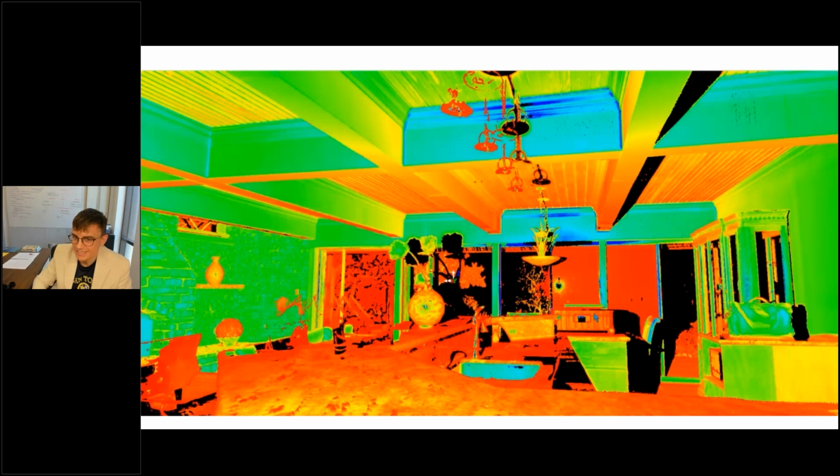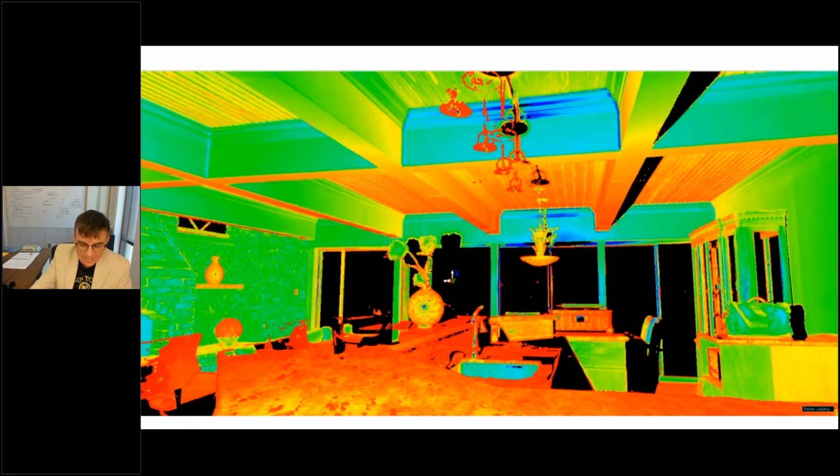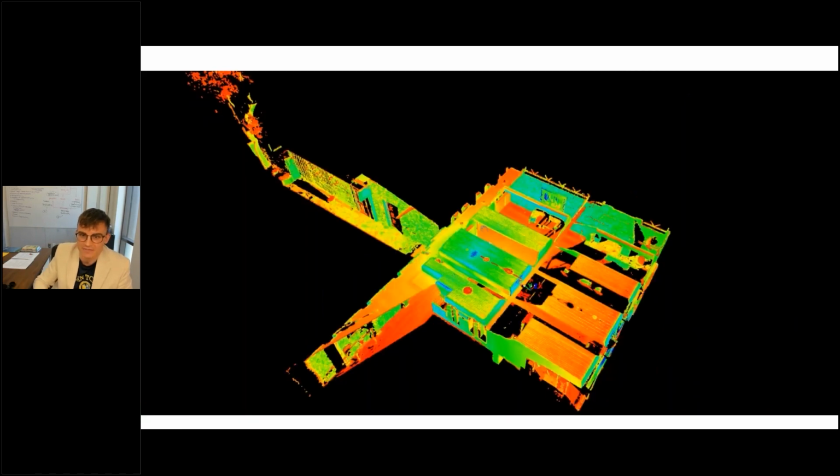So to delete reflections and refractions, draw bounding geometry. There are tools to do this in registration software. You rely on the scanner's perspective, kind of the bubble view, and you trace the boundary of the problematic surface, the frustum of the scan data. And then you just delete it. And we see that from the exterior, the scan is much cleaner now.